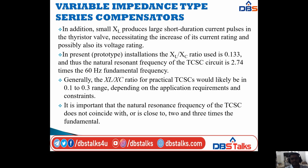In the present installation, the XL by XC ratio used is 0.1. This is the prototype, and thus the natural resonant frequency of the TCSC circuit is 2.74 times the fundamental frequency. Generally, the XL by XC ratio for practical TCSCs would likely be in the 0.1 to 0.3 range, depending on the application requirements and constraints.